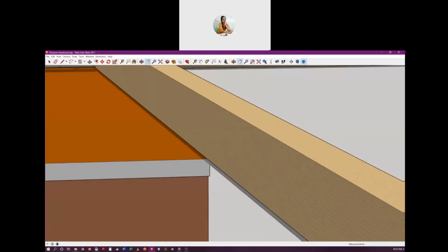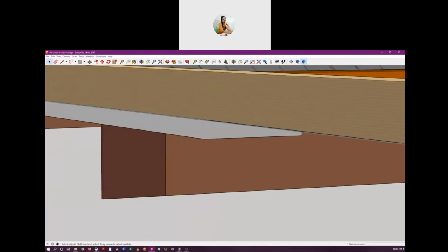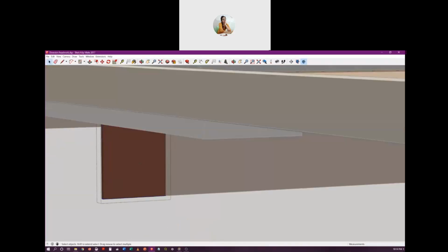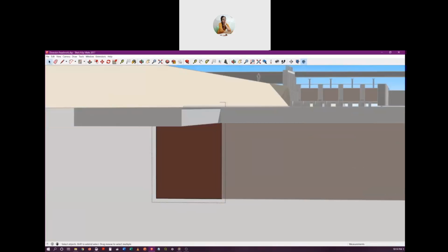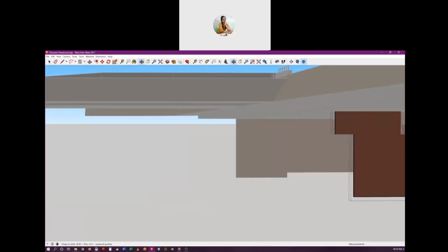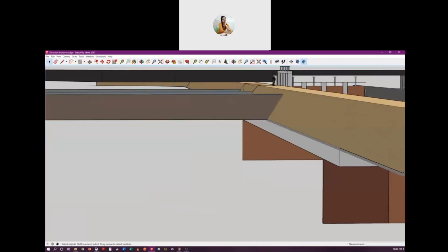This water can directly go from here to here, and that can be prevented by extending these cutoffs to a considerable length and inserting them into these embankments, so that when water tries to take this sideway, it also has to go through this longer path, because there will be cutoff in the horizontal direction also, and therefore the leakage will be reduced.